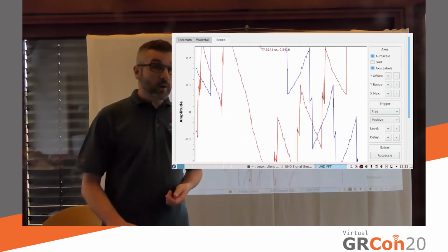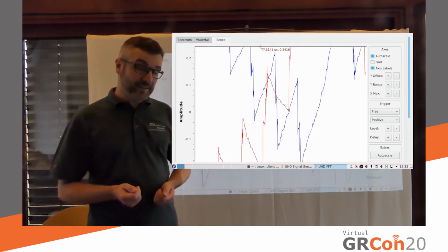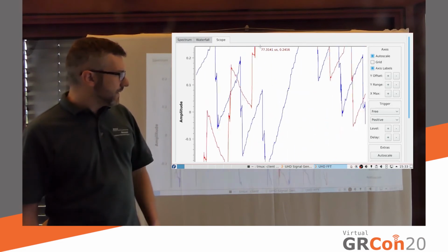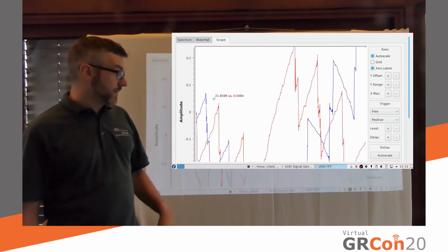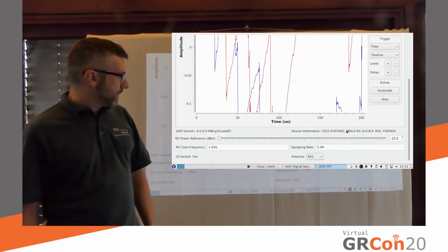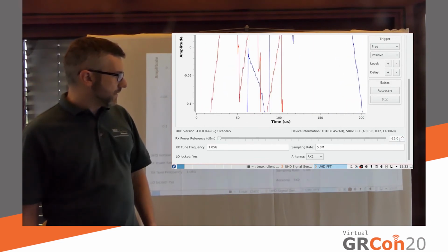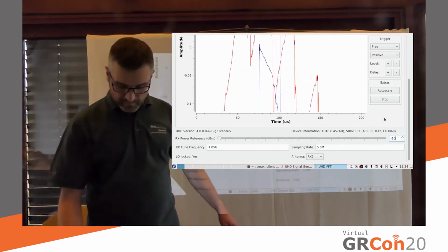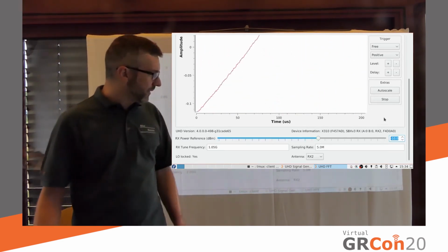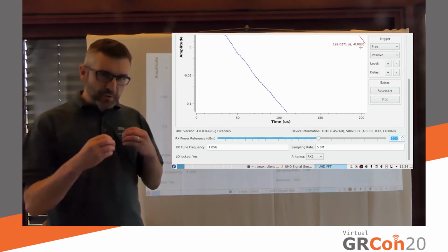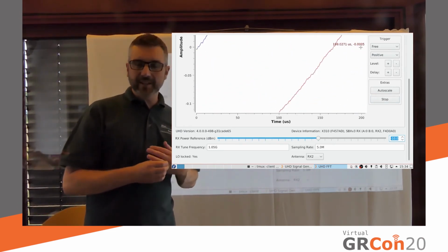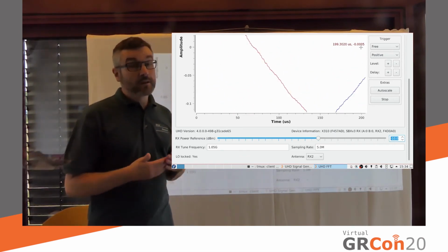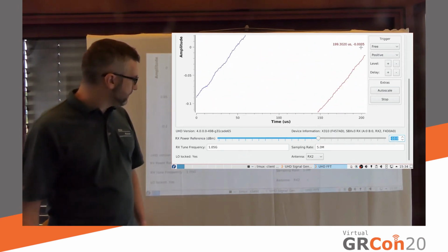So what's happening? Well, the problem is I increased my gain now, and my incoming power level is clipping the ADC. So this is no longer a valid signal. I cannot do any kind of DSP on it. So I'm going to put it back just to be safe. But as you notice, I put in -25, which is also the power of the input level. And even a theoretical perfect ADC would start clipping at that value. And this is not a perfect ADC because they don't exist. So you always want to back off a little bit.